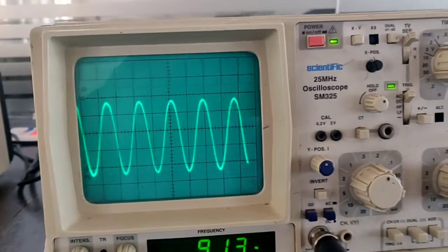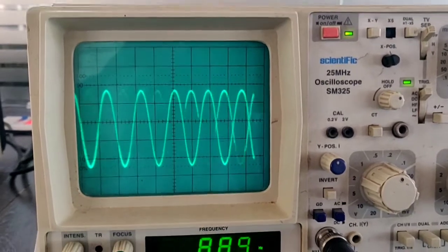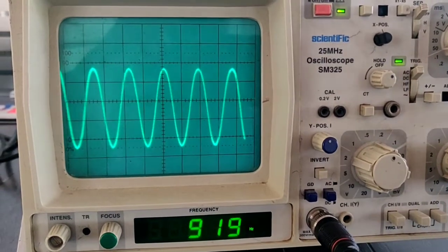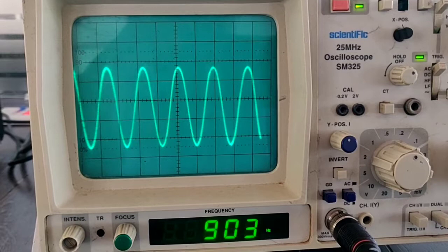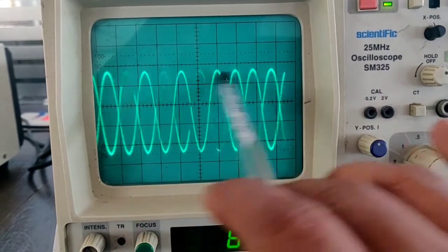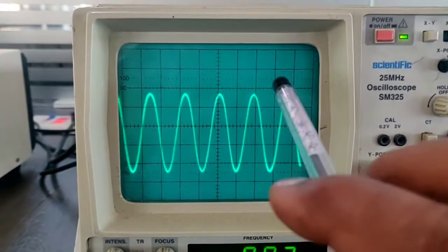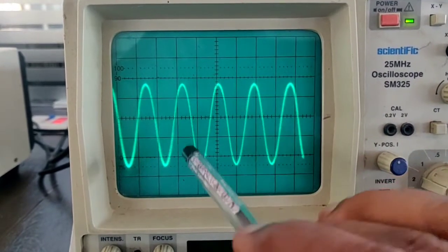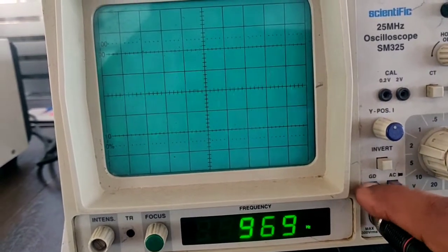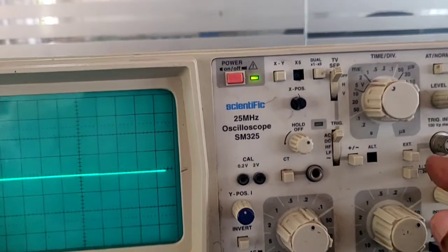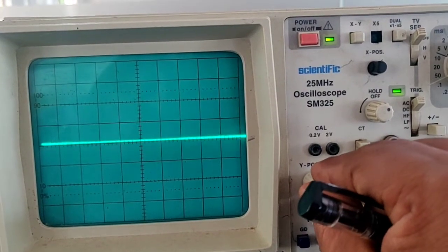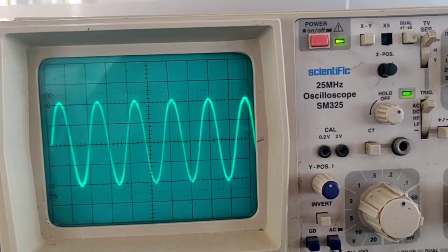See, this is an analog CRO. You cannot measure frequency directly, whereas nowadays DSOs are available, digital storage oscilloscopes, where you can measure directly and the frequency it will display. This is a basic model, and for the beginners, let us see how to measure. Because you cannot measure the frequency directly here, you can measure the time base for 1 cycle. So how to do this? Adjust this control, press the ground key and position on the x-axis, then release the ground key. Now exactly it is there.